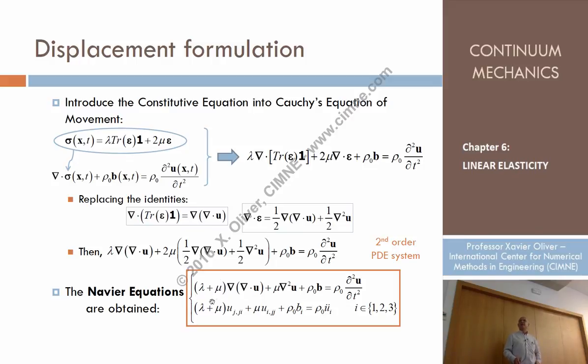You know, that's the indicial equation. Here we are using, for the first time, the notation comma ji. What does that mean? Differentiation with respect to something. So that is lambda plus mu, second derivative of uj with respect to xj, xi. And that, for instance, is second derivative of ui with respect to xj, xj, so twice, and by the way, here the Einstein notation about index repetition applies. So finally, these are three differential equations.